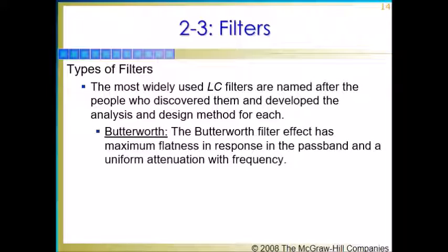Butterworth. The Butterworth filter has maximum flatness in response in the passband and a uniform attenuation with frequency. The attenuation rate just outside the passband is not as great as can be achieved with other types of filter.